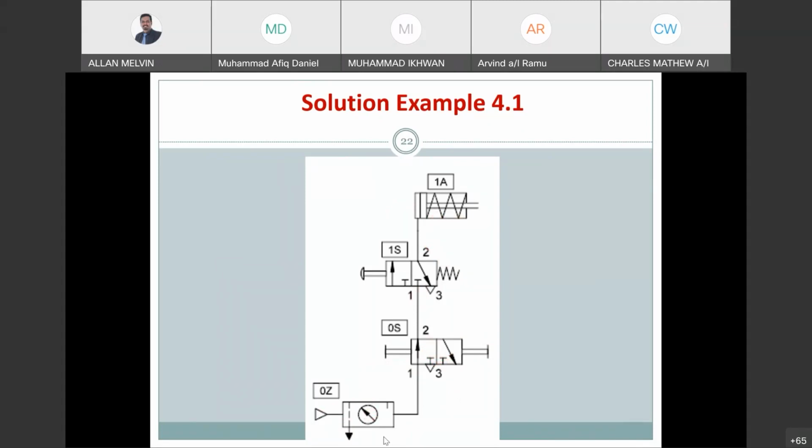Then we have learned about that in lab 2 about electropneumatic. I pun ada encourage you to keep this. So you try to disconnect the circuit by adding a normally closed contact. Sorry, in electrical, it will be normally closed. Close meaning you have a close contact. Close contact macam COVID juga lah. Close contact means you have a connection. So pneumatic normally close means no connection. With the electrical, normally close means ada connection. Okay, so you saw that.